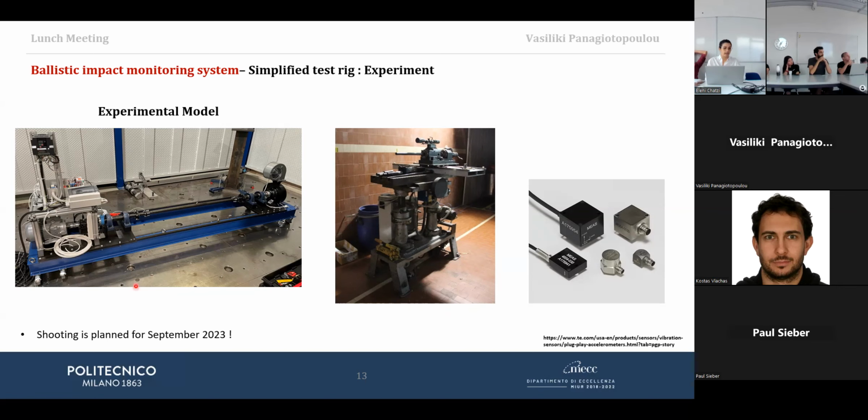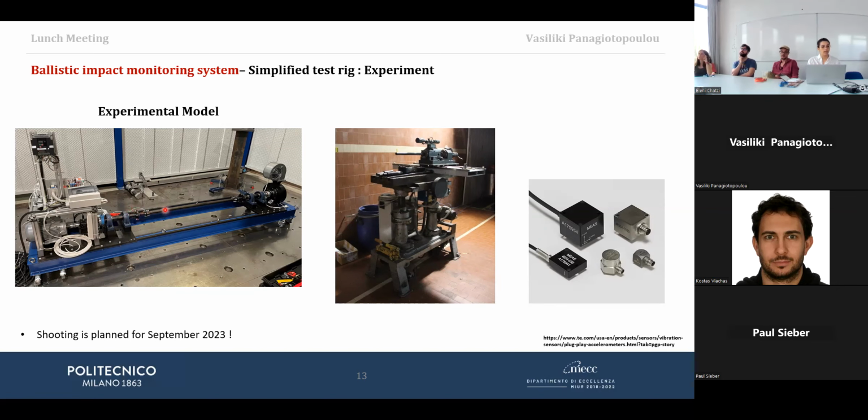What I have done here is basically take the oblique shaft along with the joints and the titanium couplings fixed on these two sides. And I have connected the motor on the left side and the brake with a fan on the right side in order to apply a resistive torque.